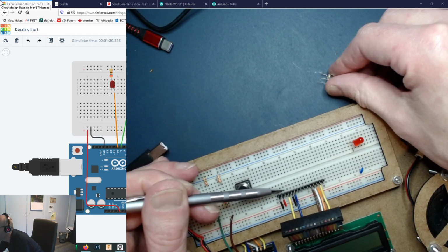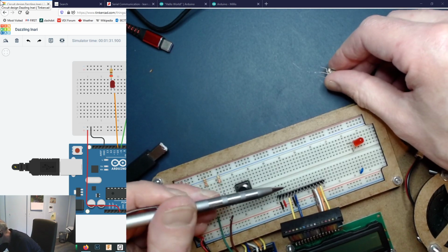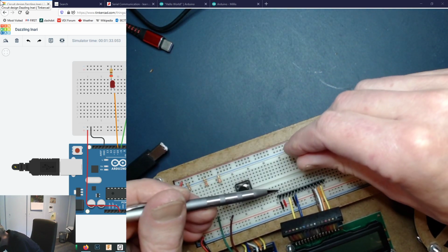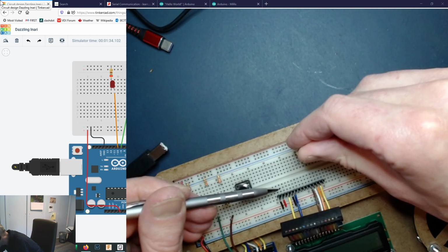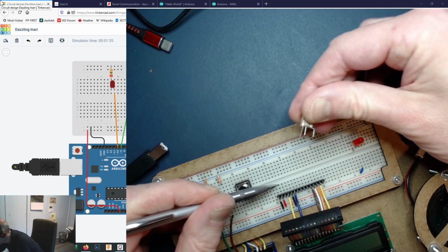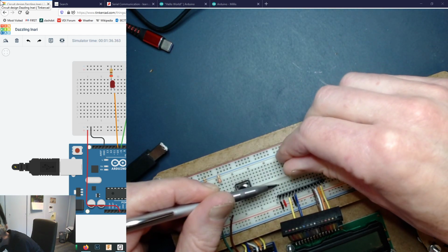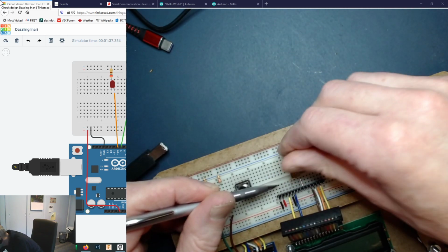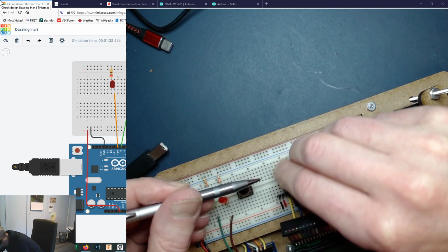Okay, so this row right here, as you can see, has nothing hooked up to it. So I'm going to take these two pins and I'm going to do a little shortcut. Instead of doing the extra wiring I did on the other side, I've got +5 coming in right here to this line. So I'm going to put one side of this into the +5, and then I am going to hook it up so that this one goes to ground. So that one goes into ground.